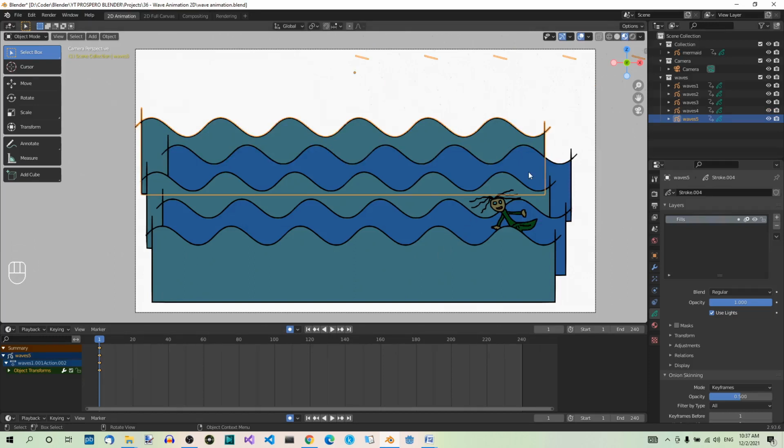If not, just add the keyframes like for waves 1. Now let's create 2 sliding cycles, each cycle consisting of the movement in one direction and back. We want one single sliding cycle to be 5 seconds long, so half the time of the animation. So after 2.5 seconds, the waves should change direction. This means we need to insert keyframes at the frames where the waves should change direction.